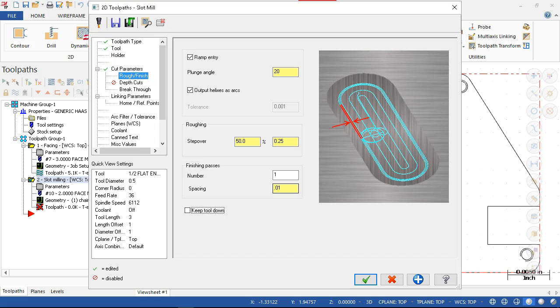All right, the less material that I put on the wall, the more chance that I'm going to have that clean surface and be able to put it on size. Downside is that it is a critical tolerance. We want that slot to be pretty tight, plus or minus 1/1000th or something. If I don't have a secondary operation, I would have to start back at the 1/2 inch tool, run completely through the slot operation to do the finish again, take the measurement. Oh, it's off a little bit. I need to take a little bit more, put a little bit more into compensation. I have to rerun the whole operation again.